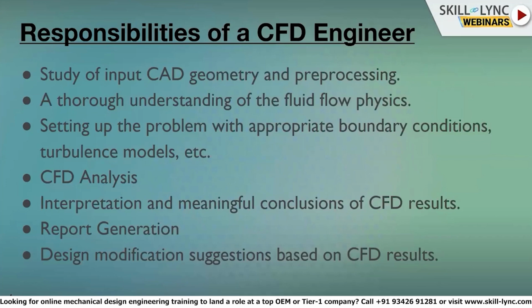First and foremost is study of the input CAD geometry and pre-processing it. When I say study of input CAD geometry, he should be aware of what problem he is going to solve, and he should know the real application of that particular problem. Then he has to modify or clean up the CAD geometry to meet the requirements of CFD solutions, and that includes CAD cleanup. Then he needs to do the meshing, then solver setup, etc.